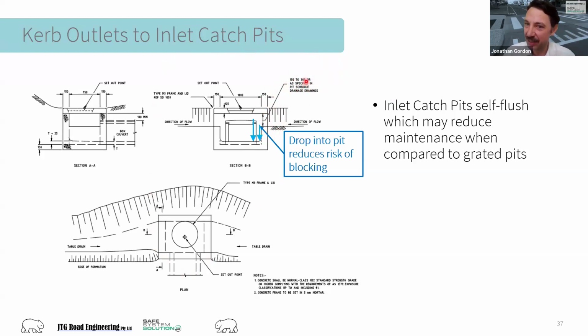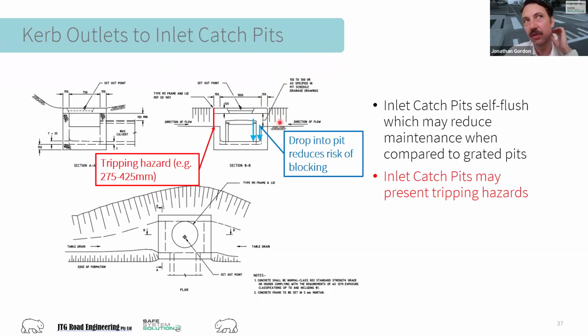But that height then has some issues, particularly for a raised safety crossing location in the roadside. If you've got something that's that high sticking above the ground, then we've now got a tripping hazard concern. I'm not saying that these work everywhere. But we are potentially putting something in a desire line where someone might be walking towards a crossing, not directly down the pathway, and this system could cause an issue for us.